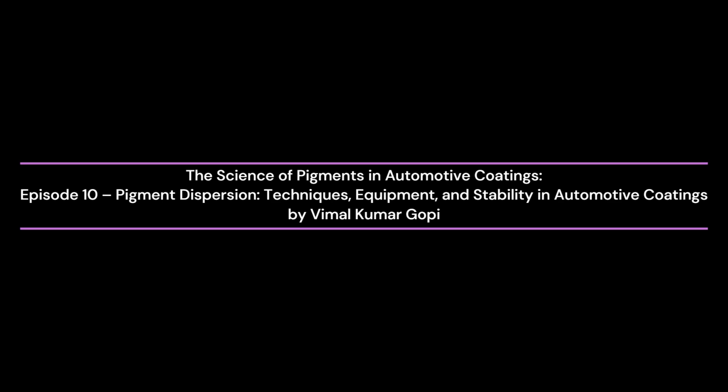Particle size reduction during dispersion increases surface area, which improves pigment-binder interaction, color strength, and hiding. However, excessive mechanical energy can damage sensitive pigments, especially effect pigments and pearlescent flakes. Flake breakage reduces optical performance, diminishes color travel, and can cause inconsistent visual effects. Therefore, process parameters such as speed, time, temperature, and media size must be carefully controlled to balance dispersion efficiency with pigment integrity.